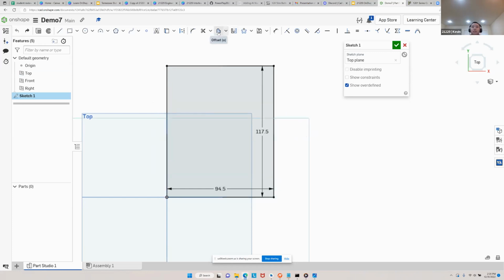So, you selected the offset tool. You can select the 4 sides of the rectangle. You'll know that you're selecting it when you see that the side turned yellow. Basically using left mouse, click on it when you select it. Then you can drag. This arrow is pointing inward, making an inner frame, but we don't want an inner frame, we want an outer frame.